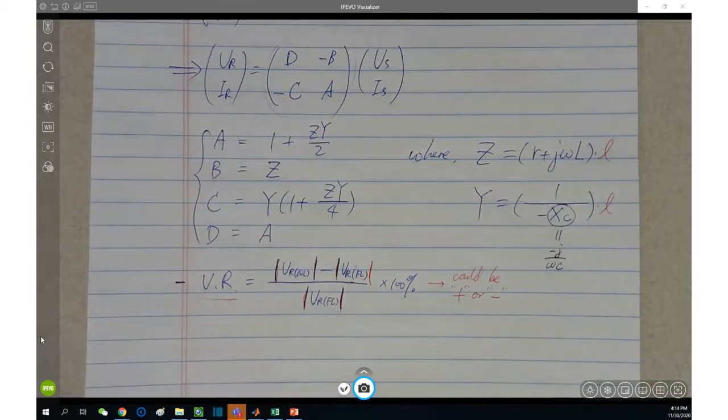That's why you're going to see a lot of capacitive load, the capacitor bank, trying to compensate the reactive power, because the majority of the load is inductive. Inductive load is going to reduce your transmission line voltage. So we compensate that with a capacitor bank.